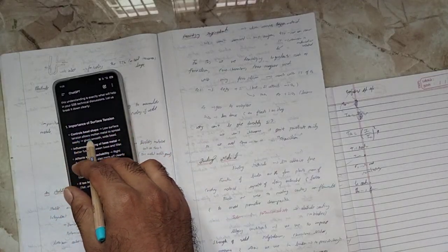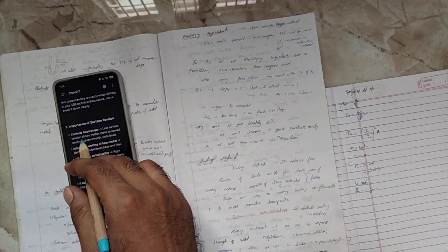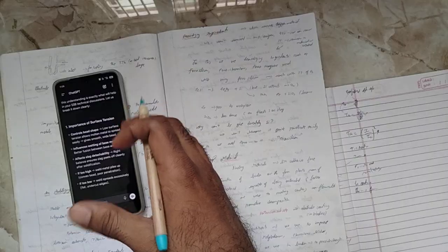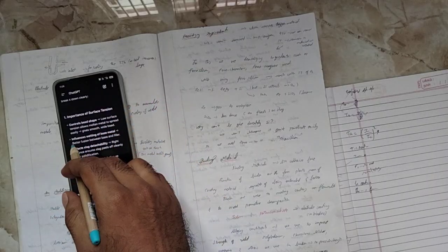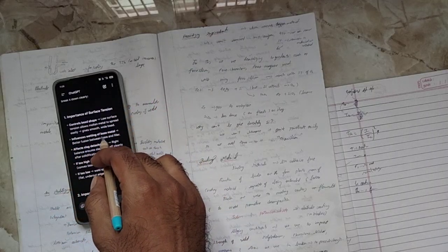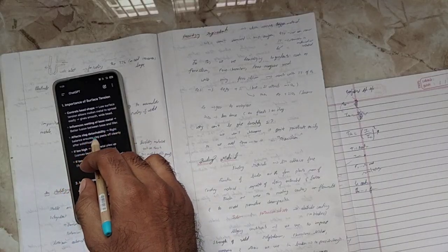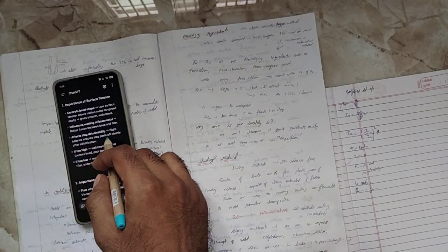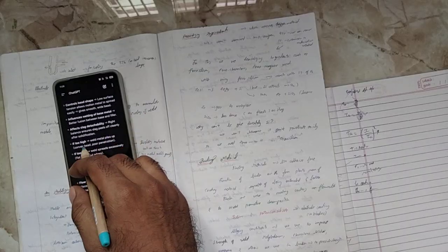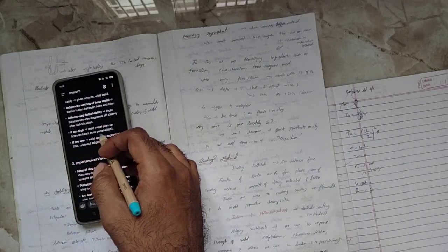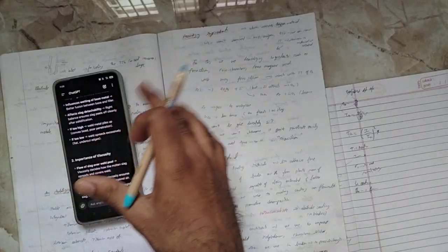Low surface tension allows molten metal to spread easily, so the bead spreads much more quickly. It influences wetting of the base metal, better fusion between the base and filler, and affects slag detachability. The right balance ensures slag peels off cleanly after solidification. If the surface tension is too high, weld metal piles up with poor penetration. If too low, the weld doesn't spread.